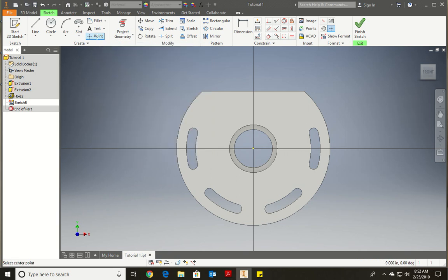We're going to place the point on the front face of the model. So where do we put it, guys? Up here or on the line? On the line. How do I know it's on the line? Because as soon as I go towards the line, my Y goes to 0. And I can click on it. There, I clicked my point.